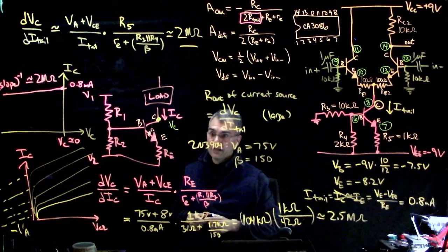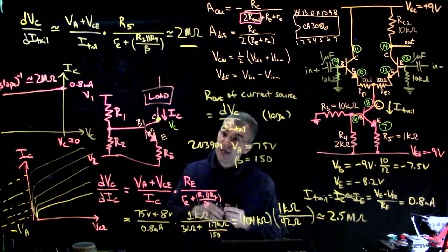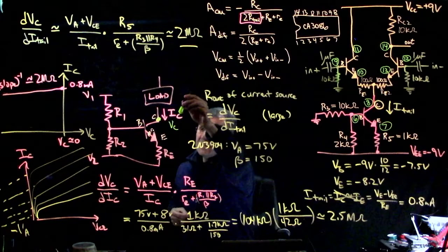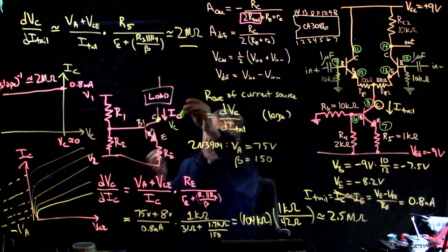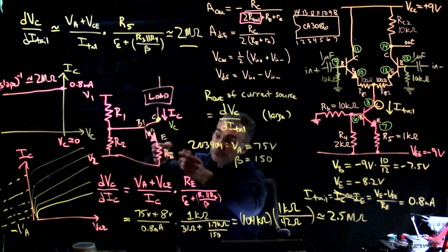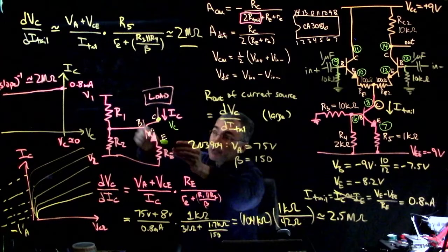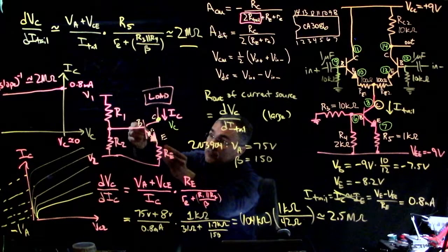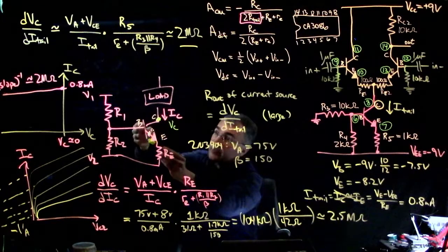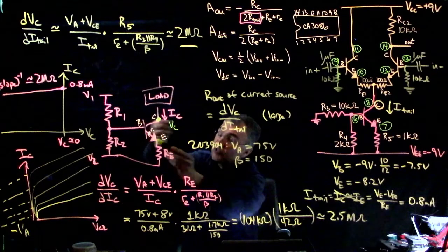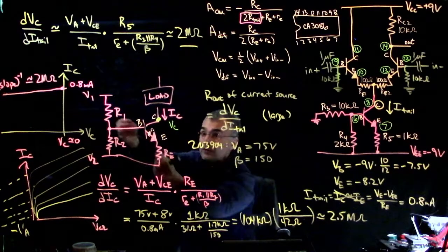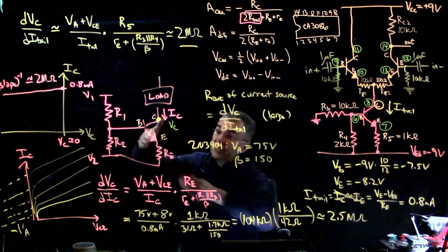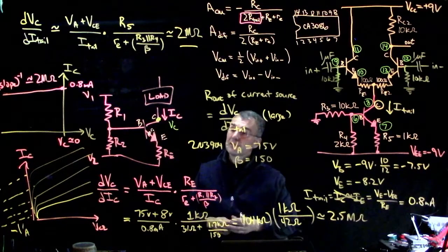But yeah, and again, we said this is a feedback mechanism because, okay, you have your desired collector current. Now suppose the collector current starts to sneak up above the desired point, then the emitter current also sneaks up, and then the emitter voltage sneaks up. But the base voltage hasn't changed much, so it clamps down on VBE. If VBE is smaller, then you know IC is exponentially related to VBE, so that makes IC smaller. So if IC gets too big, VBE clamps down and makes it smaller. And if IC gets too small, VBE gets bigger, which then makes IC bigger. So it's a feedback mechanism.